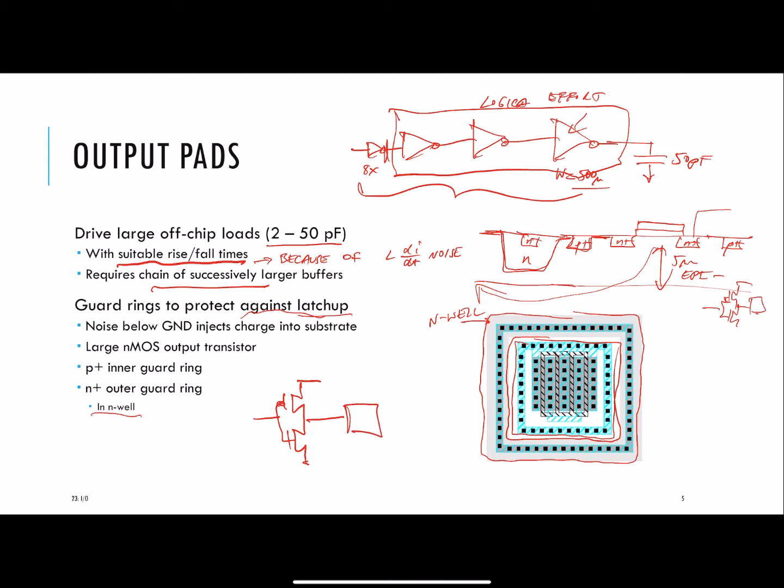We'll talk about what electrostatic discharge looks like, but I can talk about it now. Imagine you had a capacitor that's charged up to, I don't know, thousands of volts, let's say 2,000 volts. It can go up to that value because you're just dumping charge on this capacitor, and there's no place for that charge to go, just as you're walking across the carpet. Once it discharges into something, there's not a huge amount of current, but it'll take a while for this voltage to discharge. It's all about how long a period. If you can bring that voltage down very quickly, then you can smother that high voltage before it does a lot of damage.